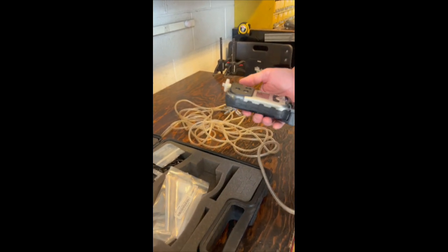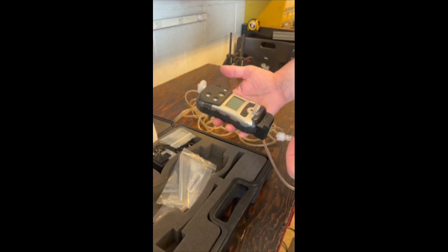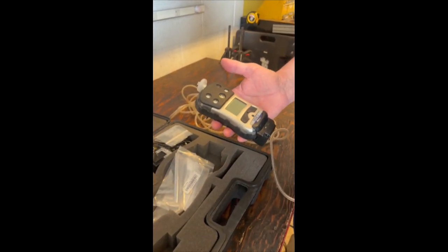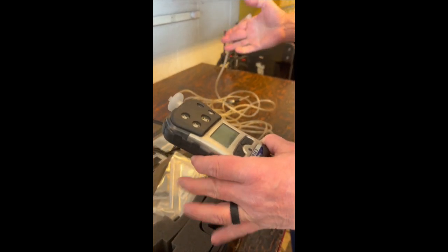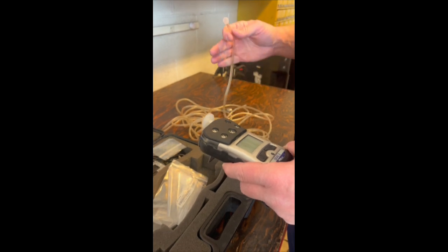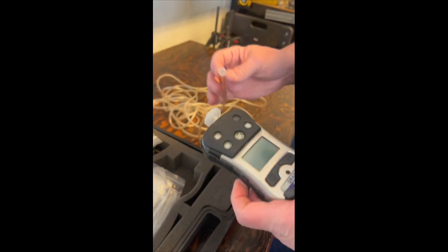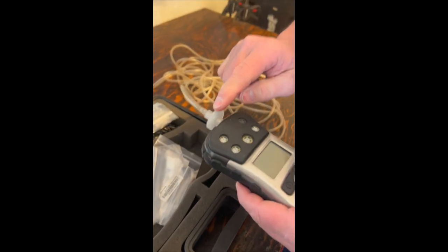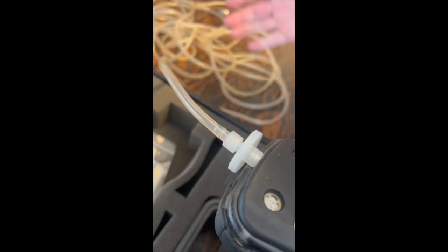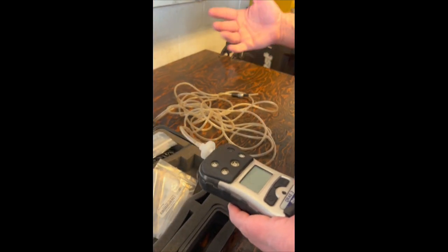There's two different monitors in the system right now, which we'll talk about. Specifically right now, though, this tubing is designed to work with the Ray monitors. When we get the equipment to monitor with the MSA monitor remotely for confined spaces, I'm sure it'll be similar and consistent as far as tubing, and the use doesn't change. So in this case, the end of the tubing simply screws onto the filter end of the CGI, and then the CGI will draw air from the bottom of the tube at whatever level you've set this to.